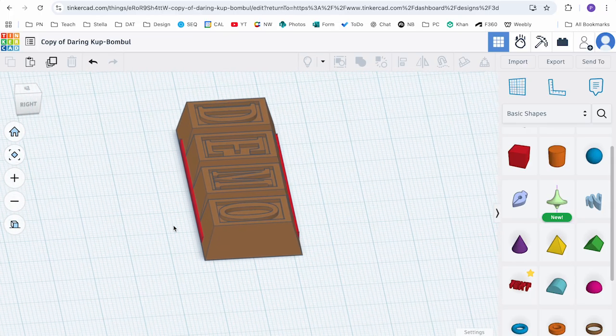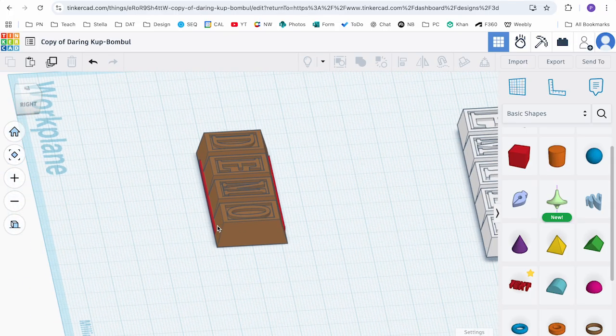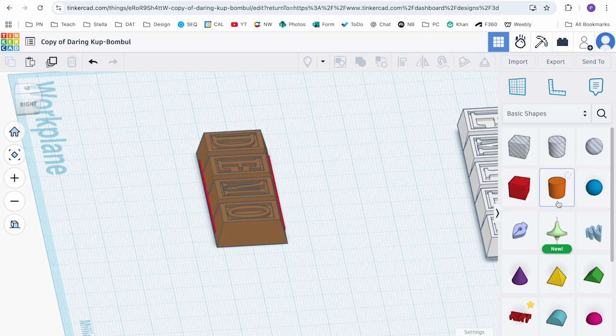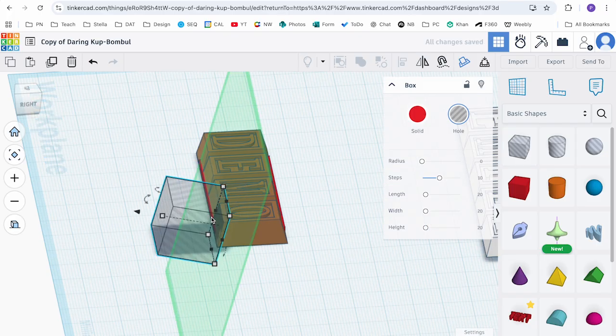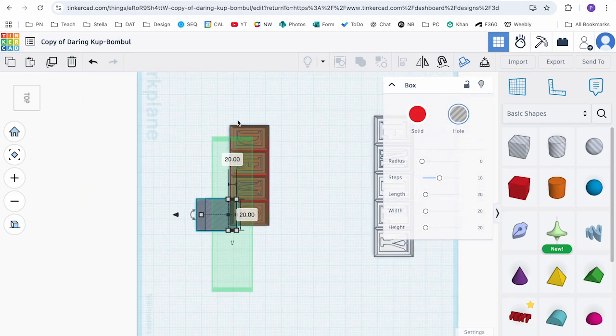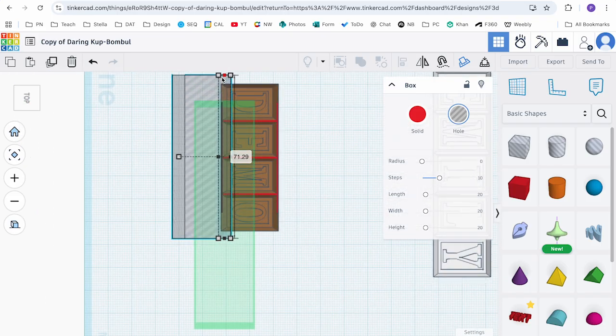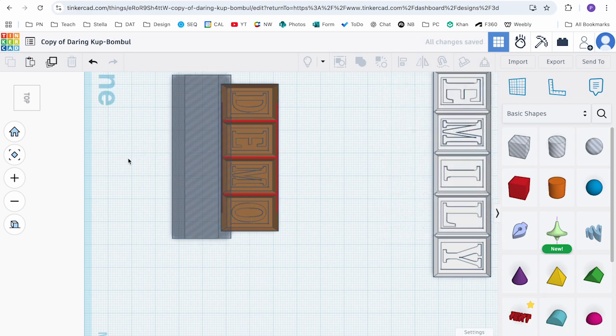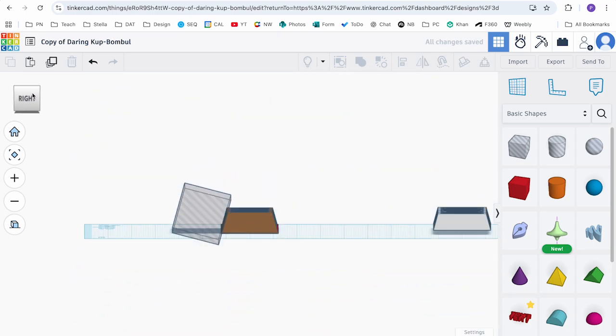We actually want to get rid of that. So what we can do is remove that with a cut box. Now, how we do that is we take our cut box, bring it over, and you can see if I drop this on that face, it matches the angle of the face. I'm going to go top view, zoom out a bit, and I can drag this across so that it now covers all those little bits that stick out.